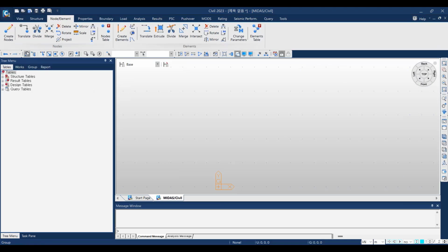After that, we can create the node. To create the node, we can go here to create node, and then we can specify the reference node. We can create it at 0, 0, 0. I can click on apply, and then you can realize that there is a node created here at the reference, the origin. There are different ways you can create other nodes here.